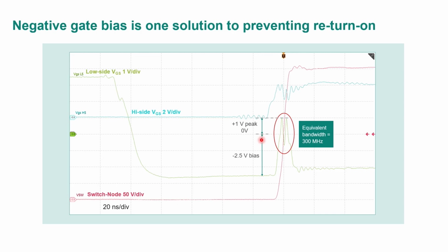So this is what I mean when I say the fast switching transients can cause a momentary shoot-through of the opposite device that will add to the current peaks, making life difficult for you trying to keep the device out of saturation. So not only do you have to worry about the datasheet limit that says 60 amps is the limit, I could perhaps make that limit lower inadvertently by some additional mistakes.